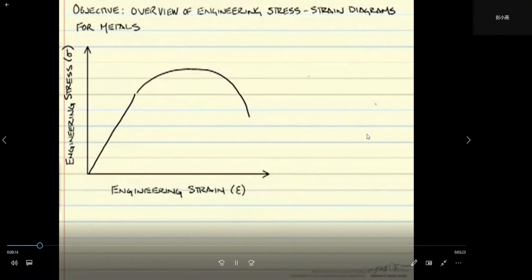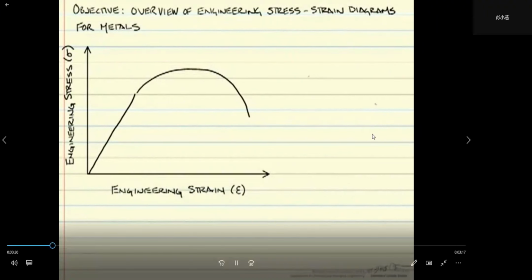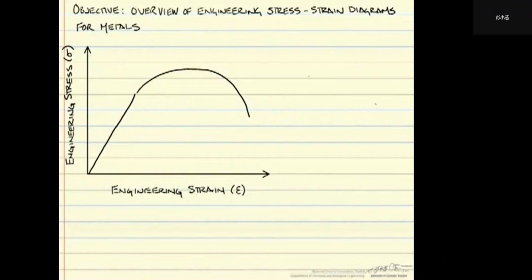Engineering stress-strain diagrams are developed from physical testing. A carefully prepared test specimen is subjected to a tensile test in a universal testing machine. The testing procedure is typically guided by a standard, such as ASTM, the American Society for Testing and Materials. This ensures that everyone who is performing the test follows the same procedure. Stress-strain diagrams allow us to plot the results from tensile tests and graphically identify important mechanical properties.